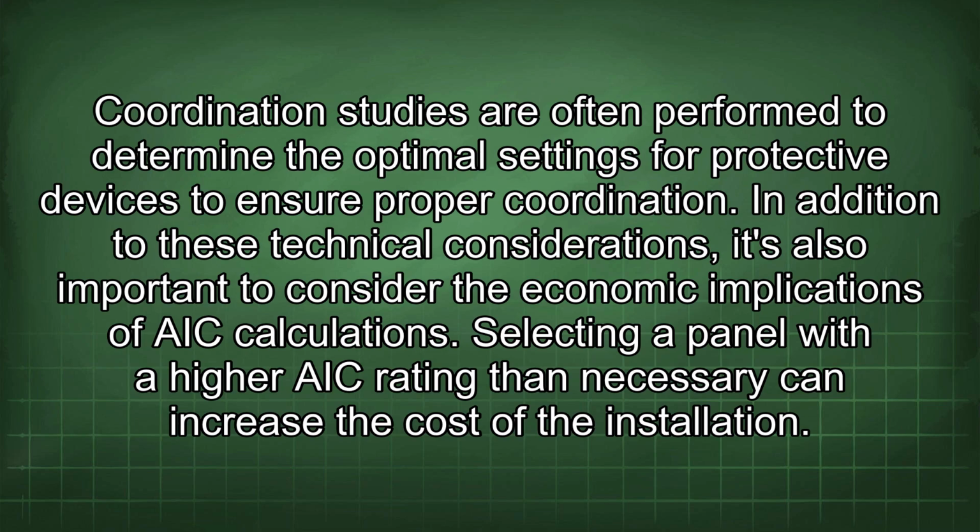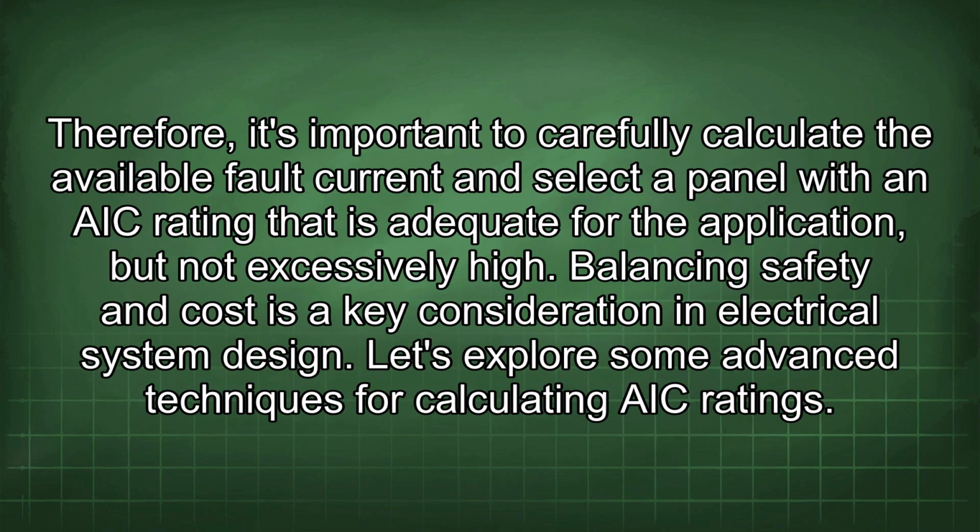In addition to these technical considerations, it's also important to consider the economic implications of AIC calculations. Selecting a panel with a higher AIC rating than necessary can increase the cost of the installation. Therefore, it's important to carefully calculate the available fault current and select a panel with an AIC rating that is adequate for the application, but not excessively high. Balancing safety and cost is a key consideration in electrical system design.